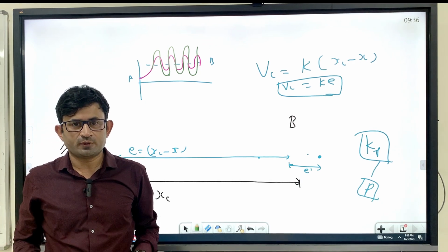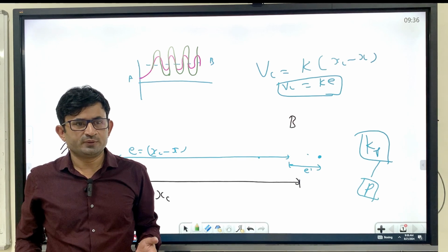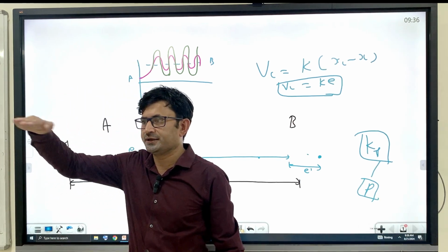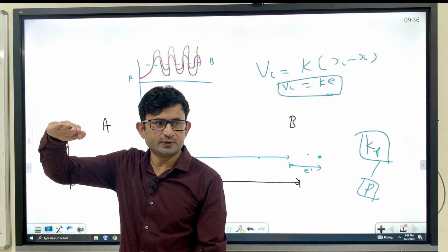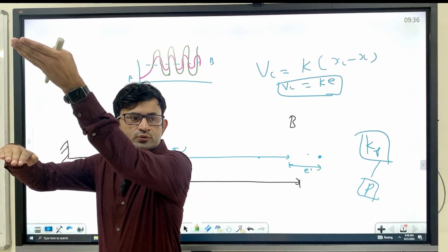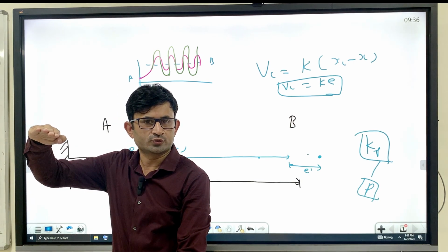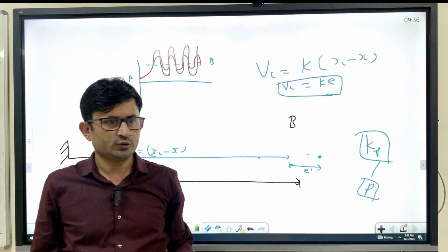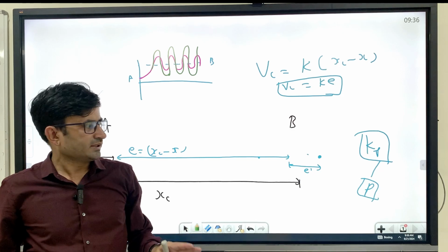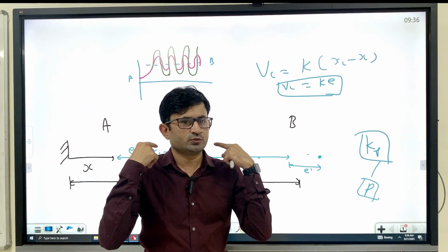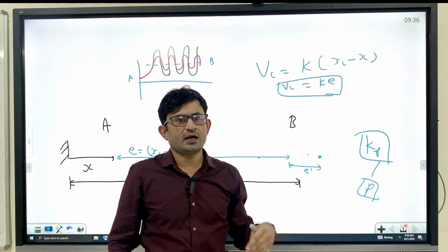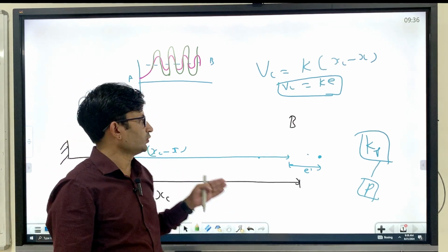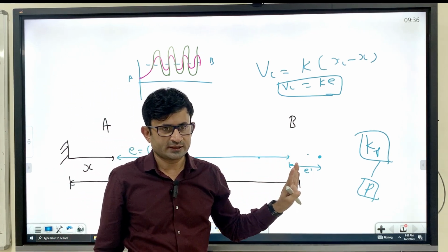And you can consider the example of a quadrotor. By simply using P, you cannot hover. Let's say this is your desired height. By using P, you will reach this point and try to overshoot, and then come back again, undershoot. So overshoot, undershoot, overshoot, undershoot will keep going on. One thing is clear: with P we can reach near the target, and we can also control the response time. By increasing the Kp value, you will move faster, right? That is clear about the P, right?